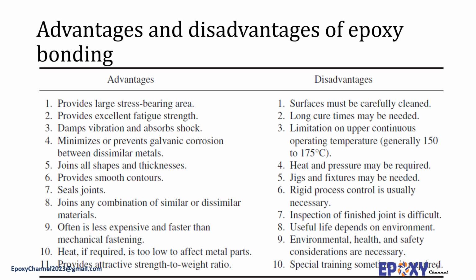However, for joining two substrates, epoxy adhesives could be the worst possible option. Like other processes, the employment of adhesives for a joining task has distinct disadvantages in specific applications. For example, the surface has to be cleaned for good bonding. Some epoxy adhesives have long curing processes. Sometimes heat and pressure have to be applied, and health issues have to be considered as well. Often a trade-off in performance, production capacity, cost, and reliability has to be considered before choosing adhesives for joining different substrates.